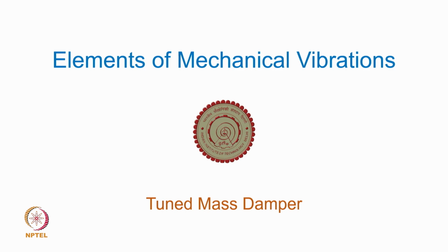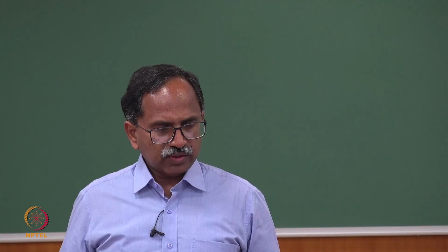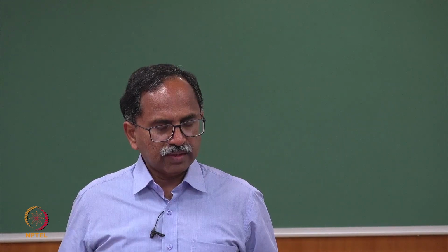But there were issues that if the operating conditions fluctuate a lot, then instead of a 0 vibration amplitude, we can actually encounter large amplitudes of vibration, because the two new natural frequencies are not widely separated. Okay. So, there are these issues of an undamped vibration absorber. So, in today's lecture we try to get around this limitation by introducing a damping element in the absorber design. So, we saw the application of an undamped vibration absorber